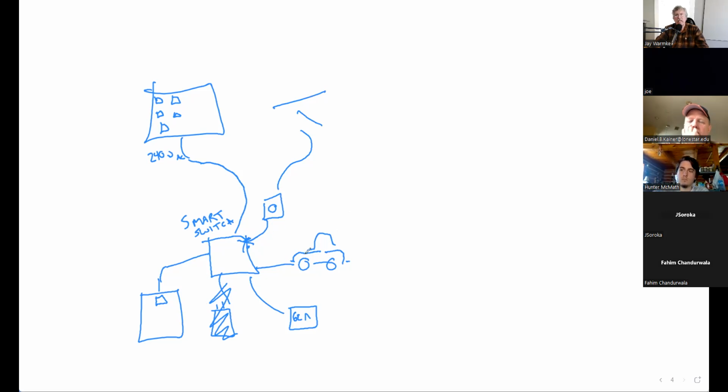Now, the other thing it does is the battery, through this smart switch, will send a signal to the array and tell it that the grid is still functioning. It will confuse the array into thinking the grid is still functioning, so these microinverters don't shut down. Because of anti-islanding, as soon as those inverters lose sight of the grid, they just turn off. So I need something to tell it that the grid isn't down. Well, it's going to use power from my battery or power from my car to convince it that the grid is still functioning. And so now I'm in standalone mode.